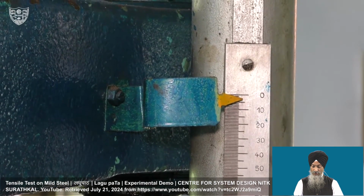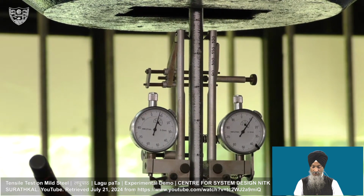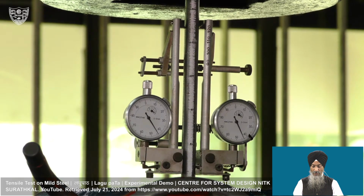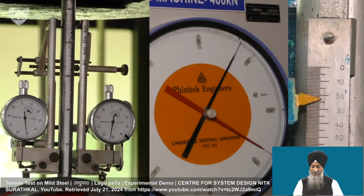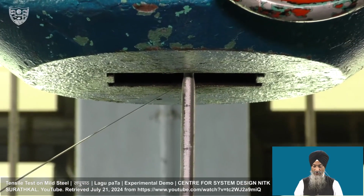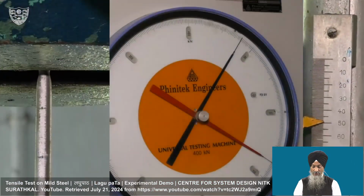You see, gradually the load will be applied, and the extensometer is showing that slowly elongation is also happening. So we keep on noting the extensometer readings at regular intervals. Manual recording is there, that is pen and paper recording. You can see the elongation is there. Then we remove the extensometer.